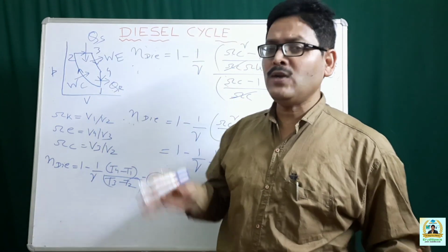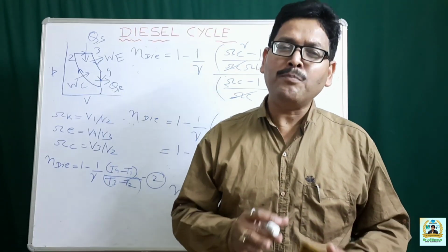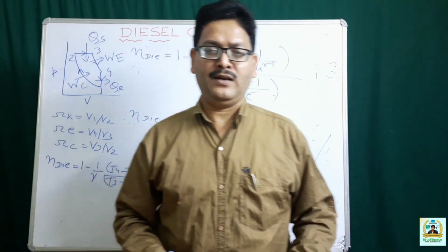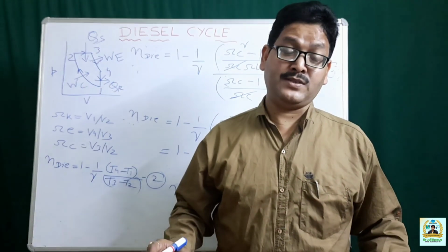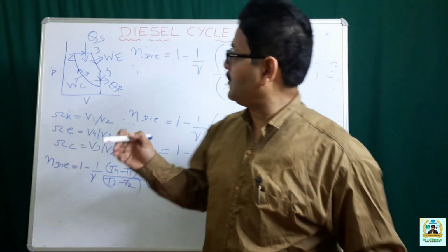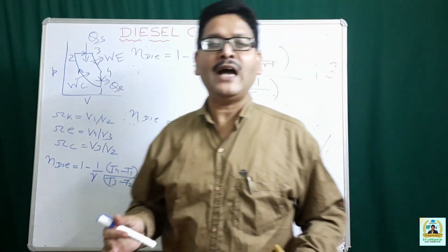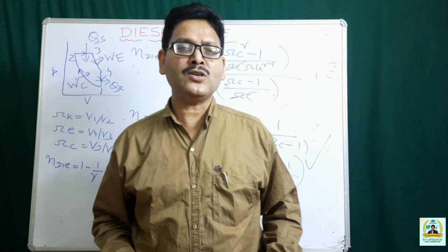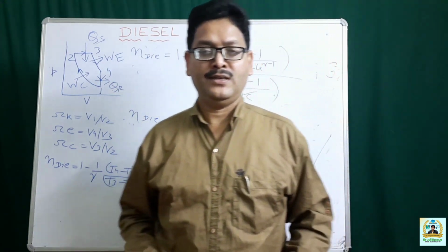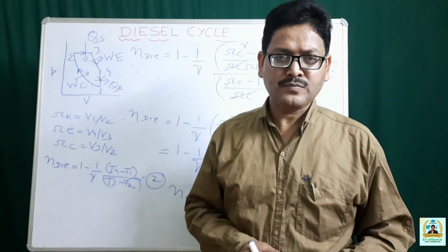But when you are going for Diesel cycle, you can keep the compression ratio much higher, because the air and fuel are not being compressed. Only the air is taken in at the beginning, and subsequently the fuel is being added. So we can have higher compression ratio and can achieve much higher thermal efficiency compared to the Otto cycle.